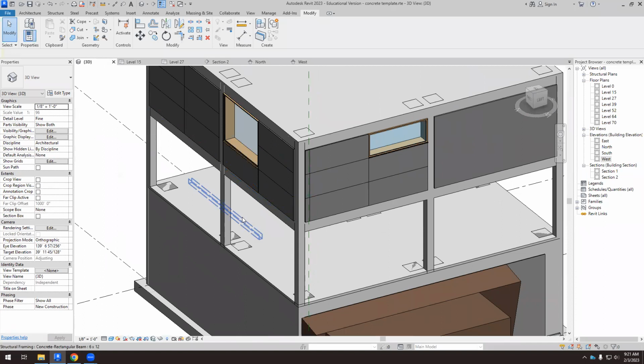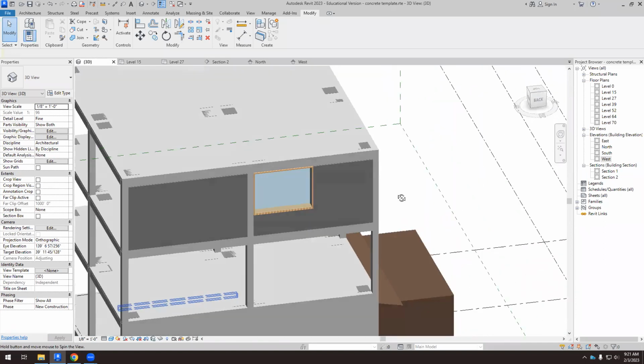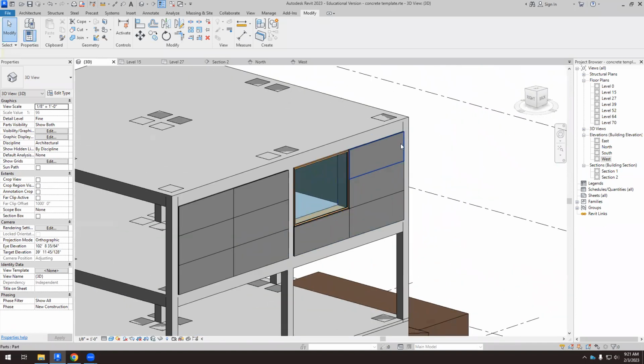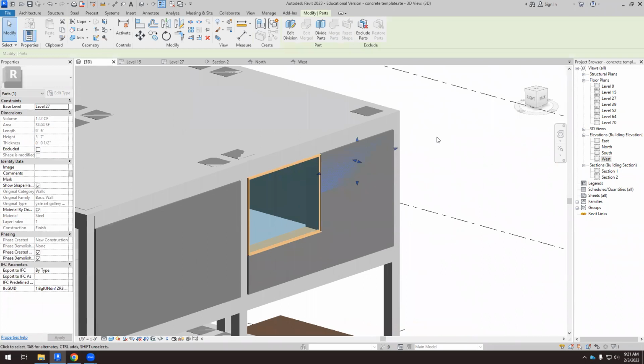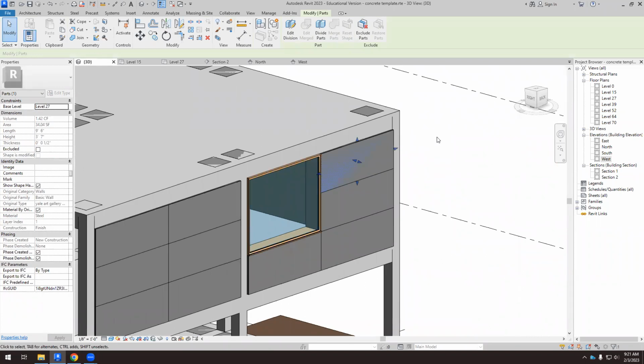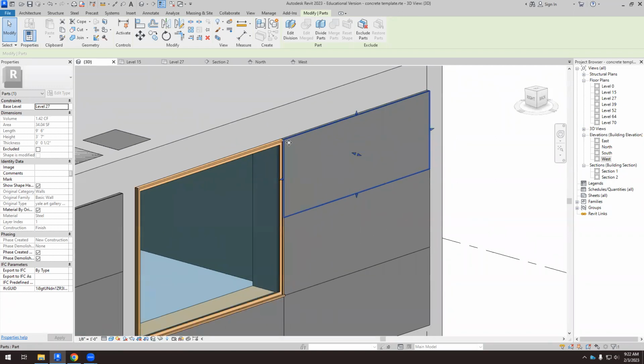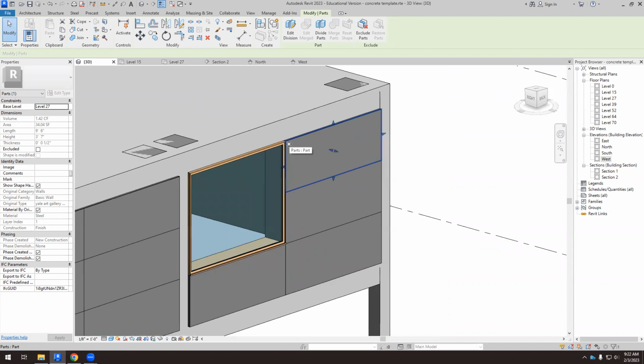If we want to fix this panel to that structure, at least we need two elements. We need a vertical element here, and we need another vertical element there. And then we can evolve this steel facade to that vertical element. We can have three. It depends on the weight of this. I don't know, maybe here with two of them would be enough.